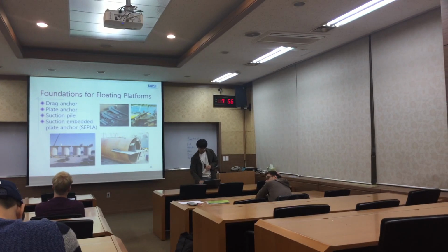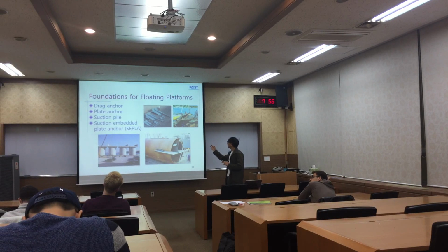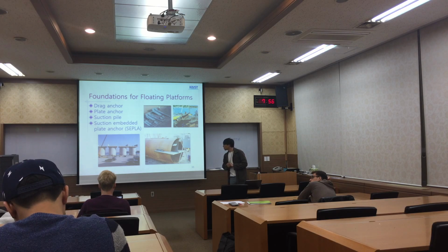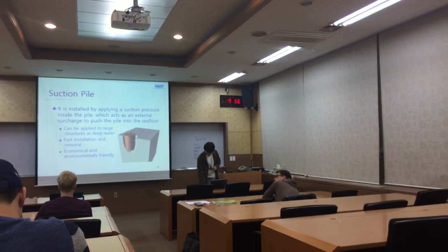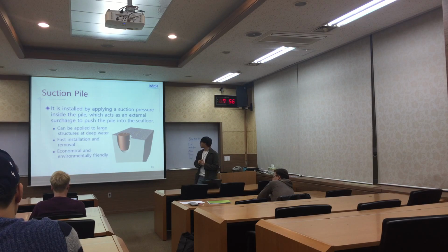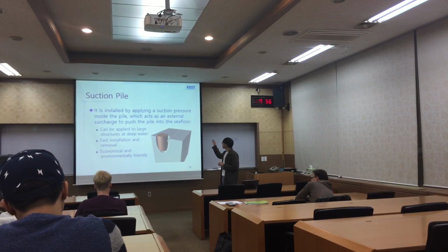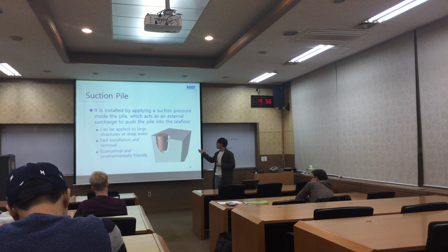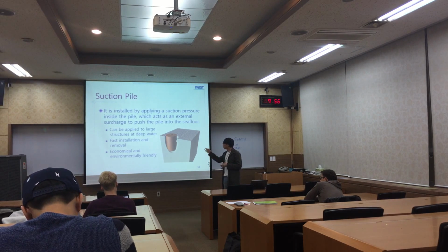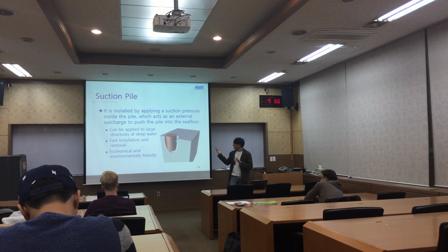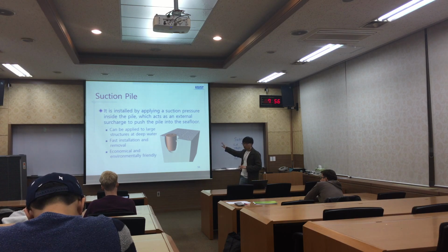And the next one is floating platforms: drag anchor, plate anchor, suction pile, suction embedded plate anchor, etc. Suction pile is installed by applying suction pressure inside the pile, and we push the pile into the seafloor. So when we install this one, it is economical and environmentally friendly.